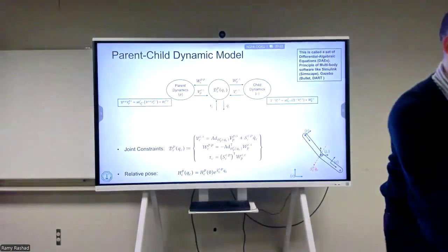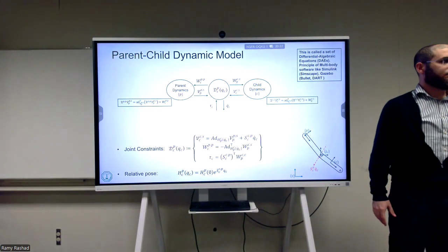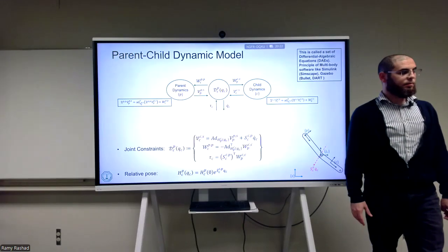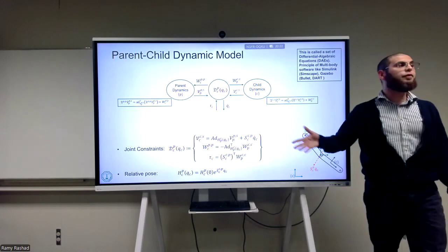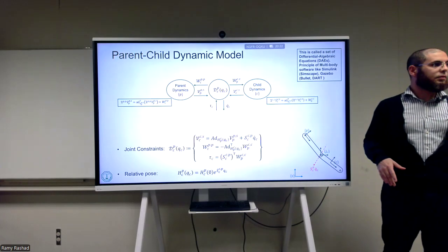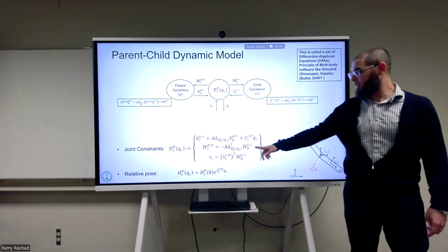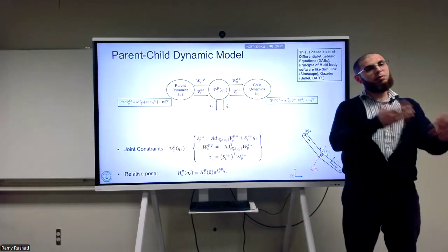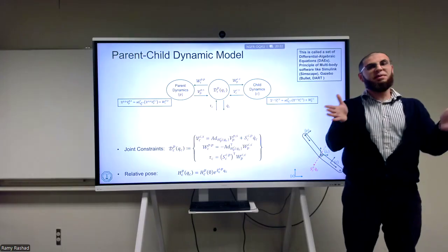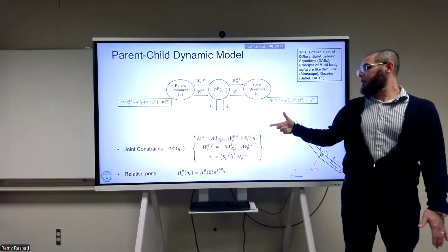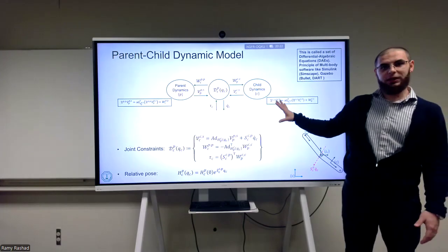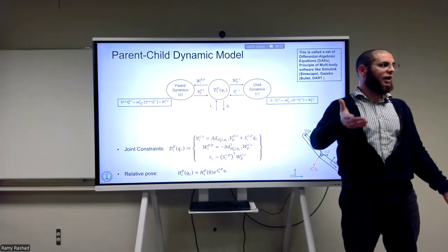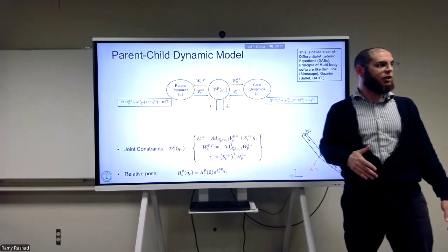Then we have limits to how we can move even within the screw axis. Yes, minus 180 to 180. That's right. Is that also presented in the equation? No, here it's allowed, free motion. When you go to the simulation, you need to say that, for example, q has some limits, and q dot has some limits, and so on and so forth. You start to put limits on the joints themselves, and the way to solve this properly speaking is that you need to solve an optimization problem. There you can put some equality or inequality constraints, and this is actually how some of the software do it.